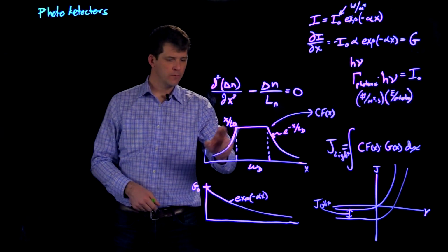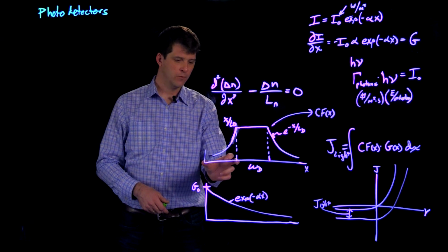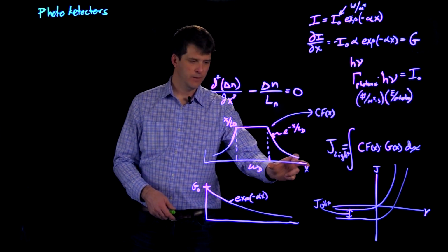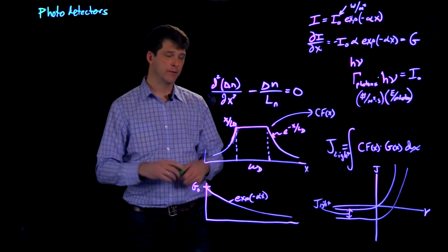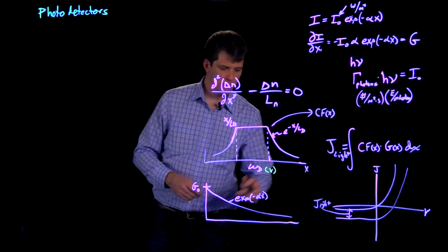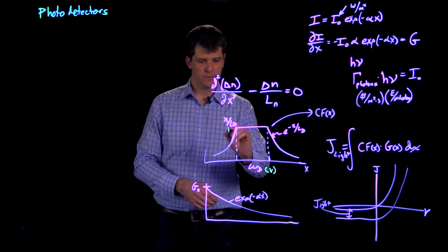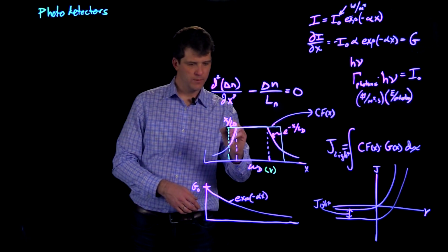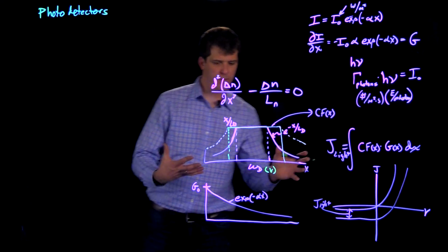So as we can see, we're losing some current here in the front of the device where the P quasi-neutral region exists, as well as in the back in the N quasi-neutral region. So we can do a few things from a design point of view and operation point of view. The first thing is, as we alluded to a minute ago, what if we apply a large reverse bias such that the depletion width expands? So now we'll make our depletion width bigger, and then we'll have the same kinds of decays going out in each direction.